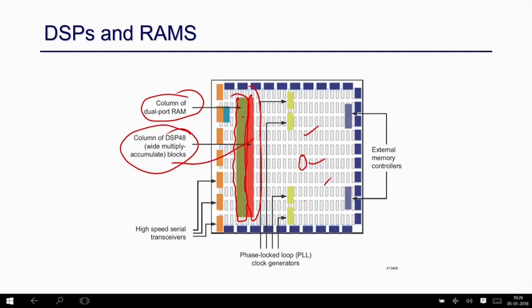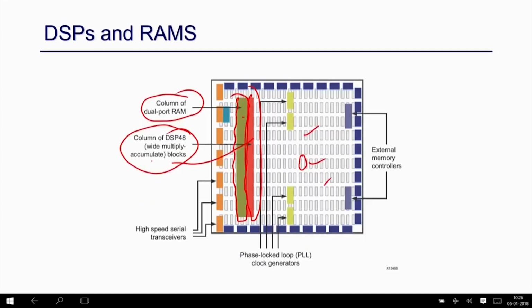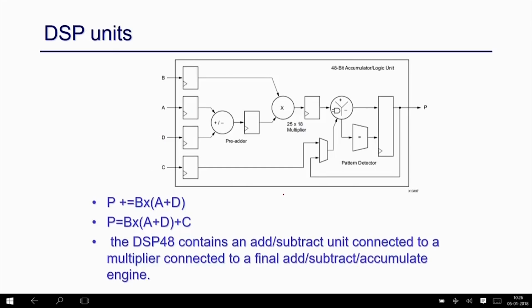And also, one register is there, which we can use to store some data, right. Now, if you go into the DSP structure, the DSP is basically a very fast implementation of a multiplier. If you look closely at the DSP block, there is a multiplier, right. The primary purpose of this DSP unit is to perform multiplication in a very fast way, right.